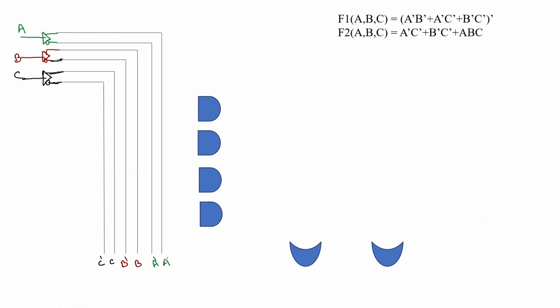Since we now have 4 product terms and this AND array is programmable here, we can use the logic wire connections. So that is the logic array. A single wire we are going to connect to each AND gate. There we mark whatever product term we have. Corresponding to whatever literals are there, we are going to take them here.